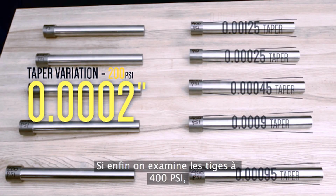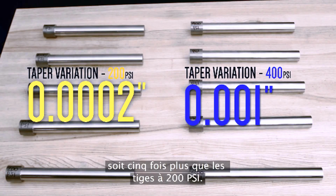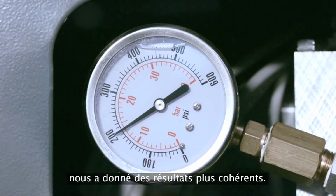And finally, looking at the 400 psi shafts, surprise! The taper variation is 1 thou, 5 times greater than the 200 psi shafts. In this case, setting tailstock pressure to 200 psi gave us more consistent results.